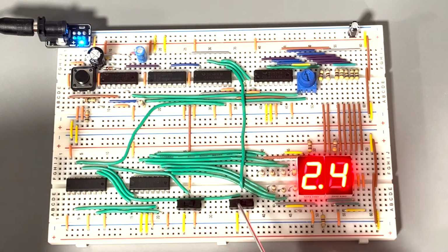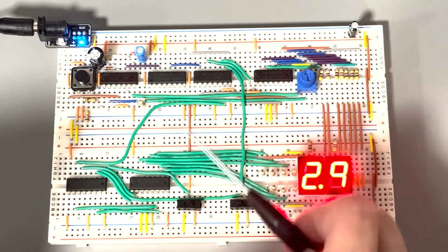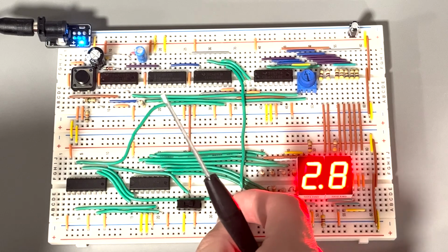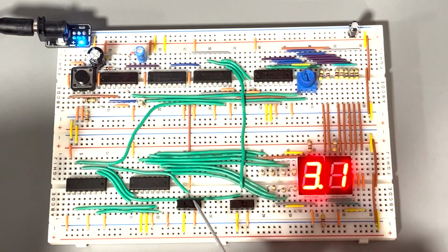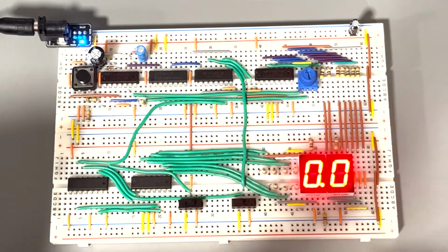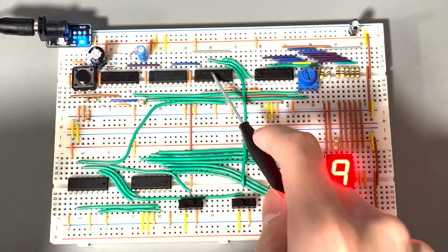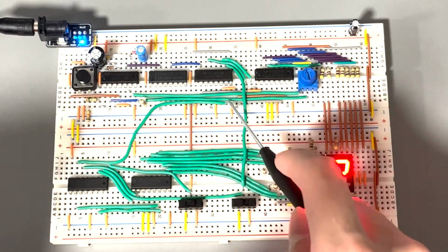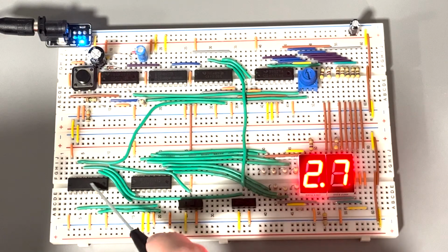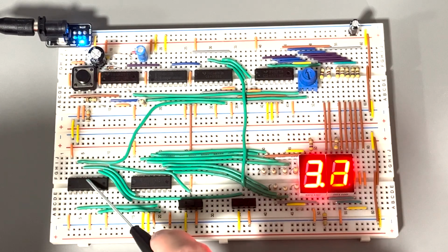There is also an up-down switch connected to both of the up-down pins for both 4510s, which can make it either count down or count up. Finally, there is also a reset switch, which can make the entire circuit reset. In order to achieve the two displays, I had to link two 4510s, utilizing the carry out pin from the first 4510 and linking it into the clock signal of the second 4510.